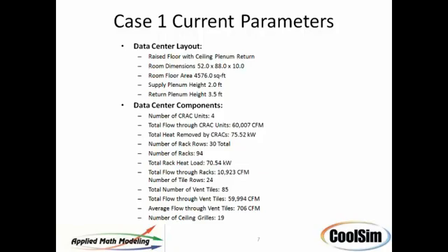Liz, it's not unusual, is it? No, not at all. And people are overly cautious. Yes. And the reason that we see it is because the data centers are often built to be able to handle max load conditions. I suspect these are 10-ton units, and there's going to be 4 of them, so they're blowing about 15,000 apiece, and there's your 60,000. So it's not unusual that you have them all running. The problem is that the energy efficiency when they all run like that is awful, as you'll see.